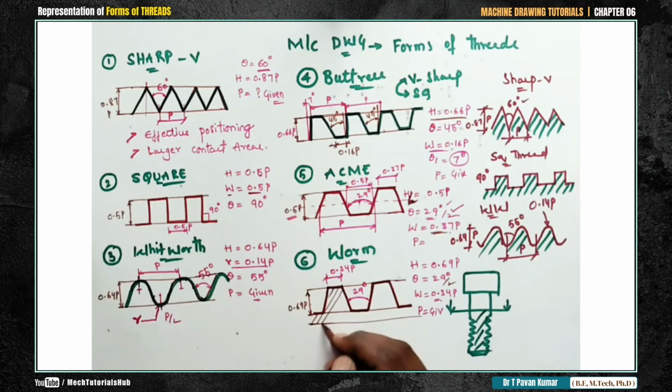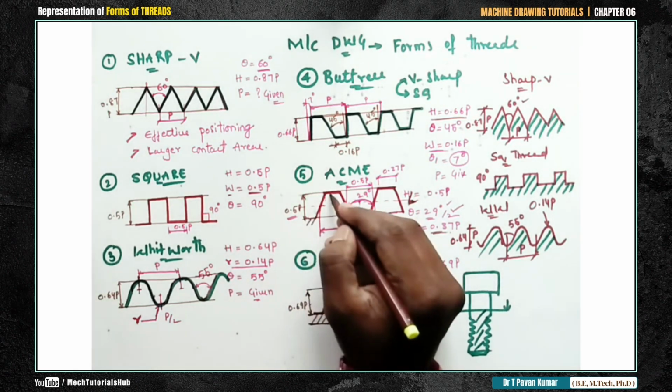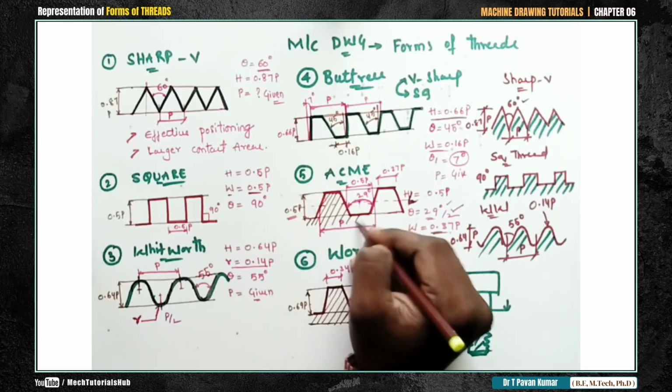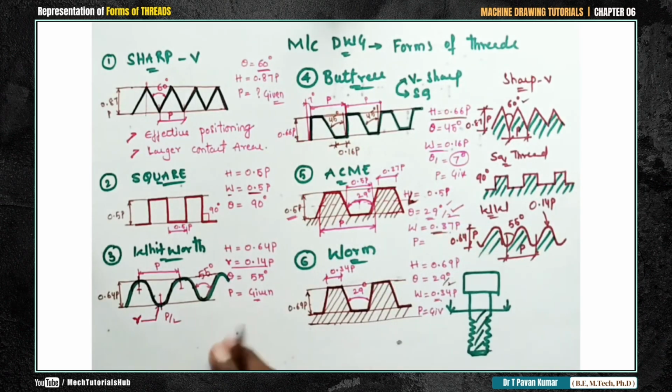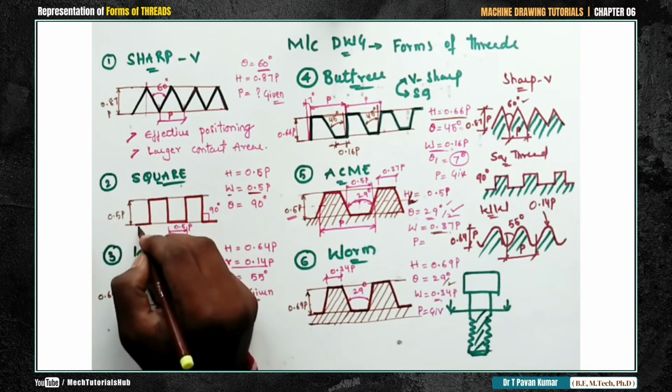Similarly in this case also 45 degrees inclination with an offset of 2 mm, okay. I am drawing it with my free hand, okay. But when you consider a drafter, you have to draw with your drafter. What you need to do is make points like 2, 4, 6, 8 maybe, okay. With your drafter, align your drafter to 45 degrees, join with all the lines which you have already marked, 1 2 3, something like this, okay.